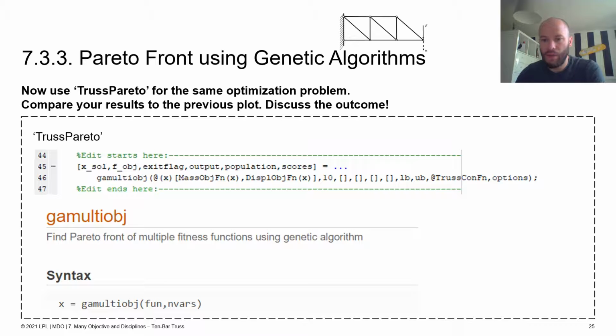They are evaluated, so the fitness function is based on two concepts. The first one is just that we are looking for non-dominated solutions, like we also had in the first exercise of today. And the second objective is a distance measure, and the distance measure is used to distribute the designs along the Pareto front. So these are the two objectives that are tried to be optimized by the genetic algorithm here.